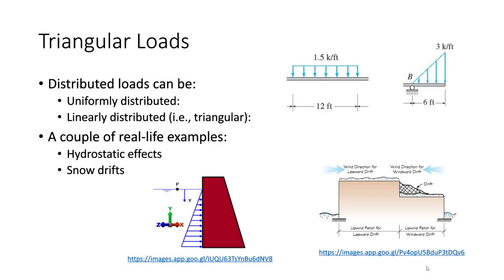That is how we deal with hydrostatic forces, is a distribution such as this. Another example that is more directly aligned with structural engineering is what happens to snow. Okay, so particularly snow drifts. So what happens is snow lands on the roof. Okay, and then wind comes. I mean, usually snowstorms have some wind associated with it, and that wind causes the snow to collect and sort of bunch up onto a given part of the roof.